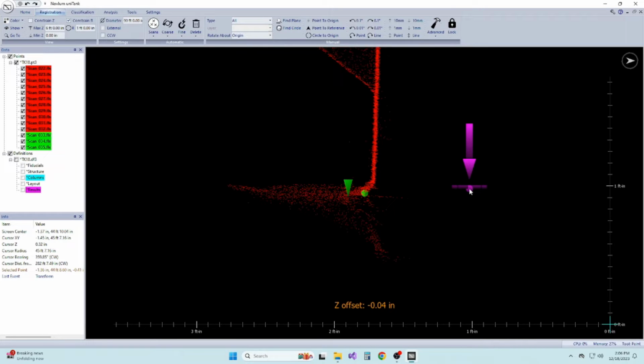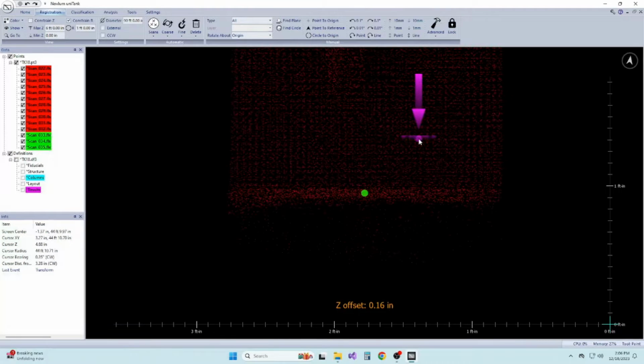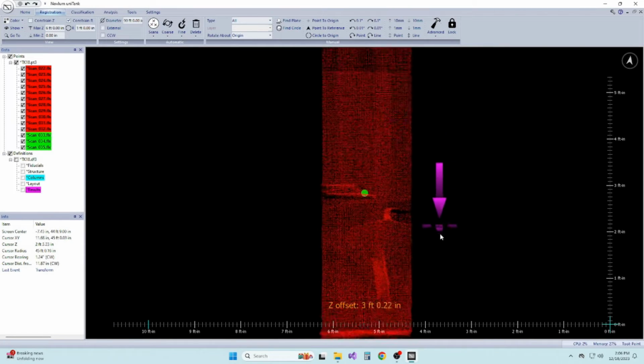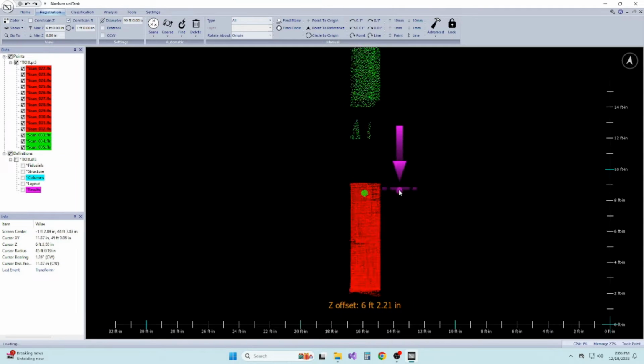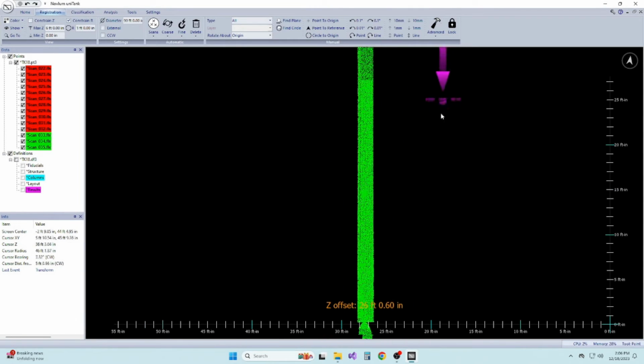So if you're using any of these physical measurements from the field, you will need to make sure that they are referenced properly. Typically, these physical elevations are measured from the tank bottom. On the other hand, liquid levels are measured from the strike. So if you are given a max fill height, make sure you know whether it's a physical elevation, such as an overflow measured on the shell, or a liquid level, such as a max fill height from a previous strapping chart. If you have a max fill height that is not based on product overflow, you can set it now.